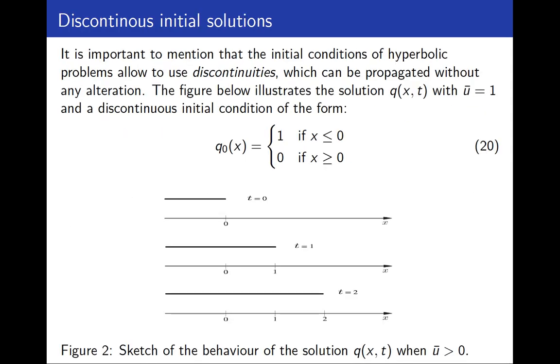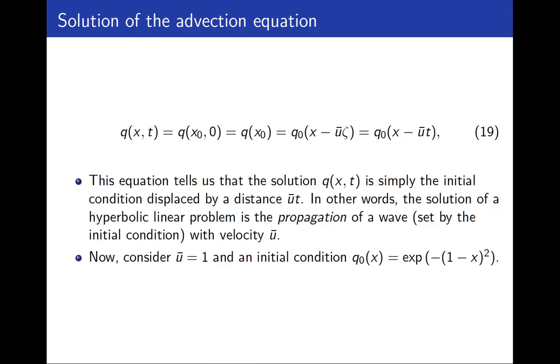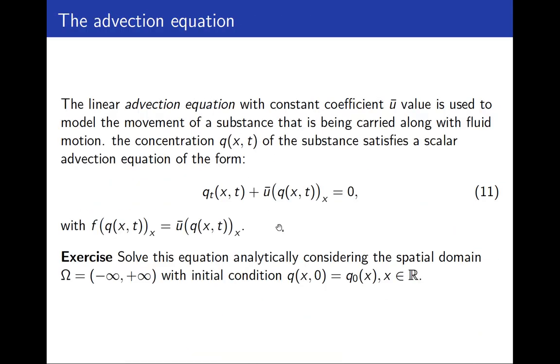Another important thing is one disadvantage of the finite difference method. We could try to use the finite difference method to solve this equation, because it is very simple, a linear equation. But the accuracy of those methods relies heavily on the local derivatives in the problem, because to evaluate the derivatives in the finite difference method you need to apply Taylor series, which have to be evaluated at a close point, a point of interest.